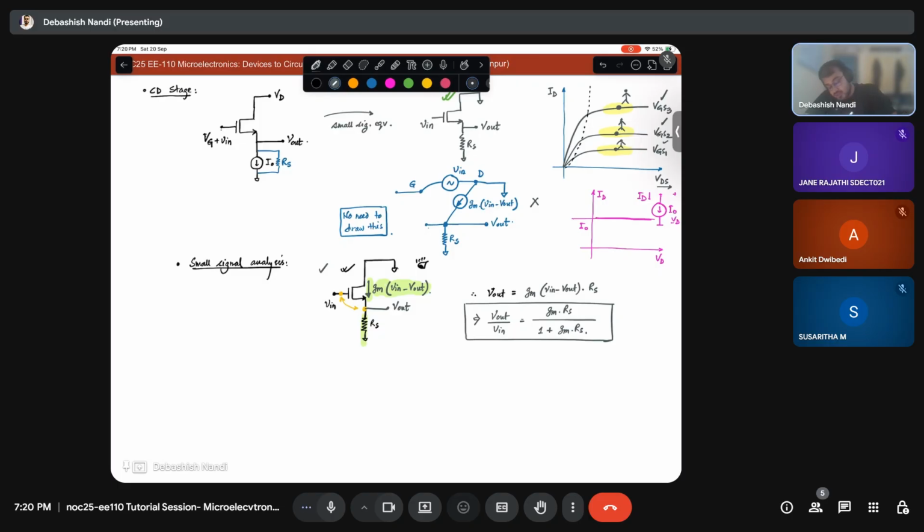So in this case, what do you think the relative value of Gm and Rs can be? GmRs is basically your gain of a stage, some transconductance times some resistance. GmRs is a unitless quantity. So generally, your GmRs will be much greater than 1.